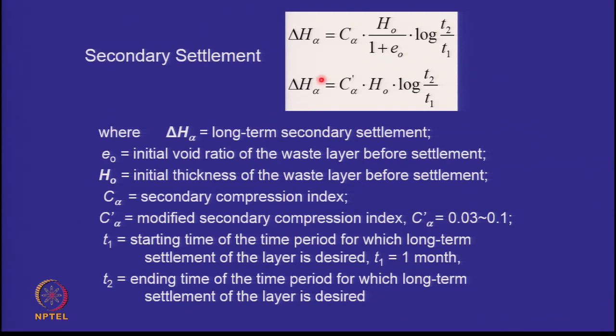We also talked about the settlement of landfills, both the base and at the top, and for the first time we talked about time dependent settlements due to biodegradation of the material, and we talked about this being very significant in comparison to the primary and the secondary settlement of the soil beneath it.